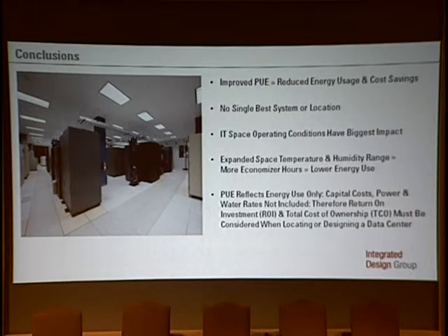So in conclusion, improved PUE relates to reduced energy usage and cost savings. There's no single best system or location, and the IT space operating conditions have the biggest impact on PUE. And that's because our expanded space temperature and humidity range relates to more economizer hours, which relates to lower energy use, which in the end relates to lower cost.